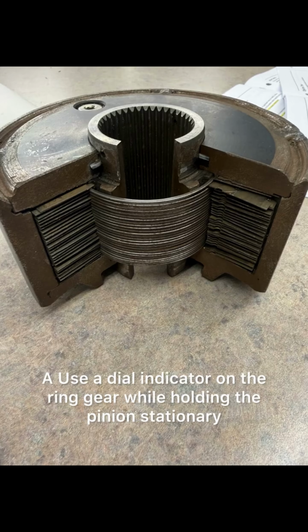25. What holds an axle shaft in the housing on a C-clip axle? A. C-clip inside the differential carrier. 26. What causes clicking on turns with a solid axle? A. Worn axle shaft splines or worn side gears. 27. How do you check pinion bearing preload? A. Measure rotating torque on pinion nut with inch-pound wrench. 28. What causes a chirp noise on takeoff?